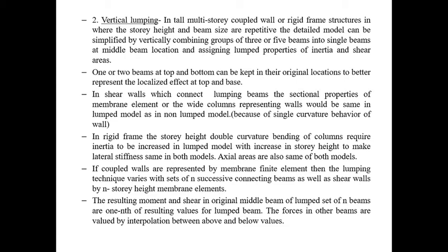So here, the beams which are similar throughout the height, we can combine in groups of 3 or 5 beams into a single beam at the middle beam location and assign the lumped properties, that is, of inertia and the shear areas.